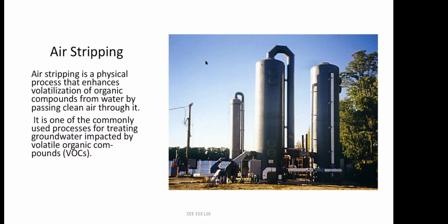But now there is always a challenge. If you let it escape to the air, you are also polluting the air, and you don't want to inhale those volatile organic compounds, which are also kind of carcinogenic. So what people do is actually capture those gases. Normally how it works is you have this kind of bead bed here. You put lots of beads with high surface area, and then you spray water here, and then you blow air from the bottom.